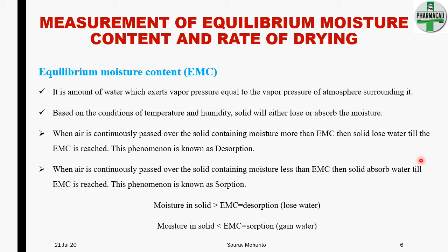This phenomenon is called desorption. Suppose there is a solid with moisture more than the EMC, and air is continuously passing through it. That solid will lose water.